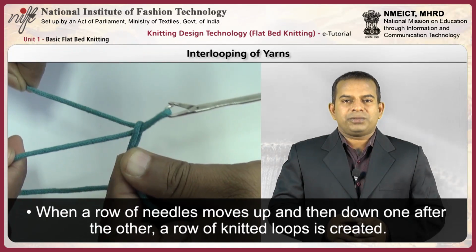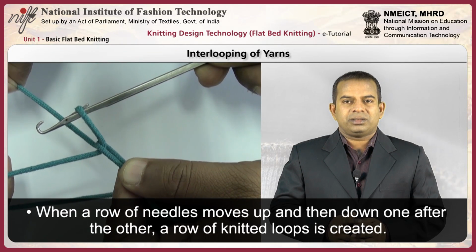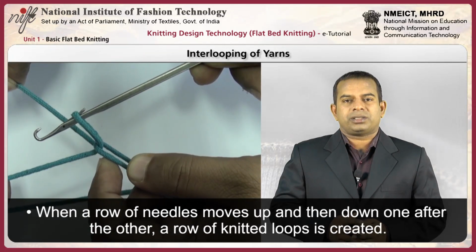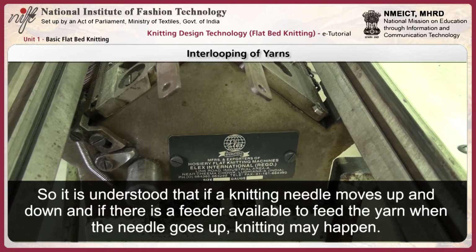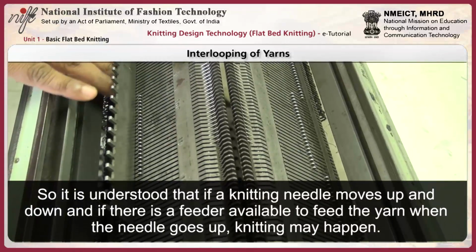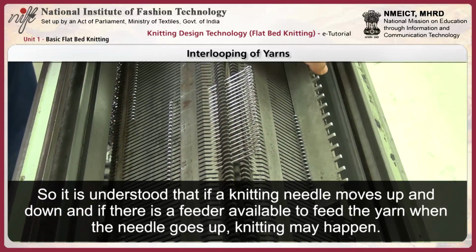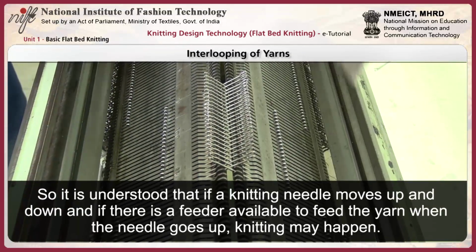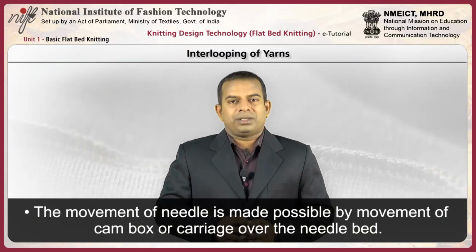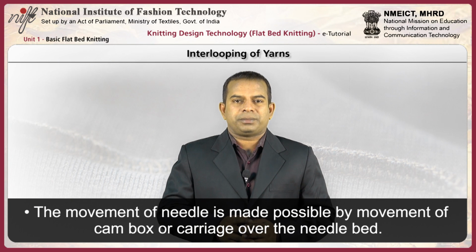When a row of needles moves up and then down, one after the other, a row of knitted loops is created. So, it is understood that if a knitting needle moves up and down, and if there is a feeder available to feed the yarn when the needle goes up, knitting may happen. The movement of the needle is made possible by the movement of the cam box or carriage over the needle bed.